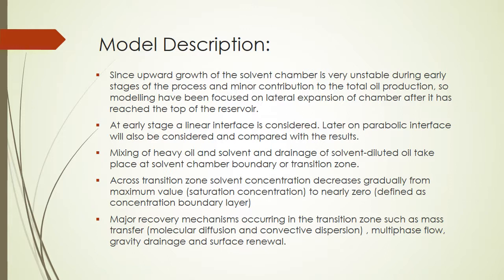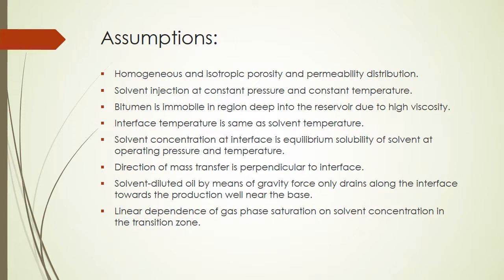Across the transition zone, solvent concentration decreases gradually from the maximum value, that is the saturation concentration, to nearly zero, which we define as the concentration boundary layer. The major recovery mechanisms occurring in the transition zone are mass transfer, including molecular diffusion and convective dispersion, multiphase flow, gravity drainage, and surface renewal.